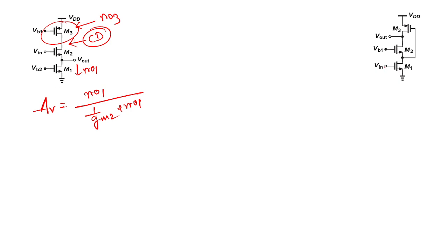So you have to think about how you can solve this problem. Just take this voltage Vx here, so this will also be Vx. So this current will be minus GM3 into Vx, and here you can take RO also. So some outgoing current will flow in this direction, and here also an RO resistance is present.